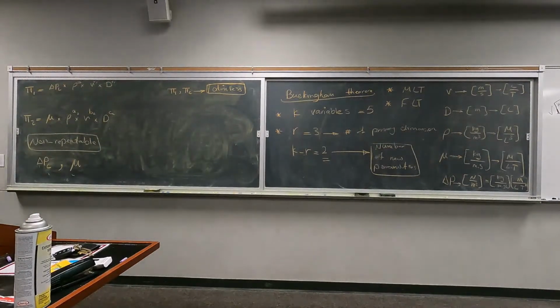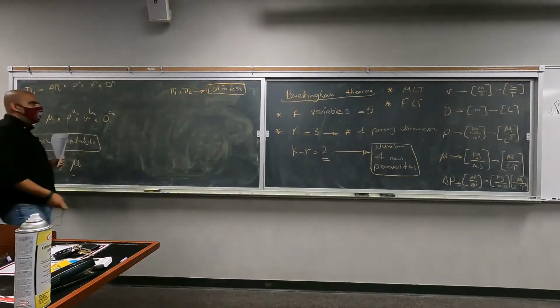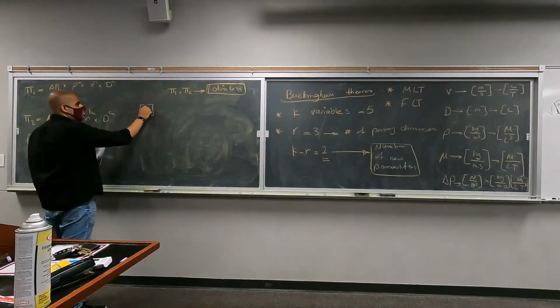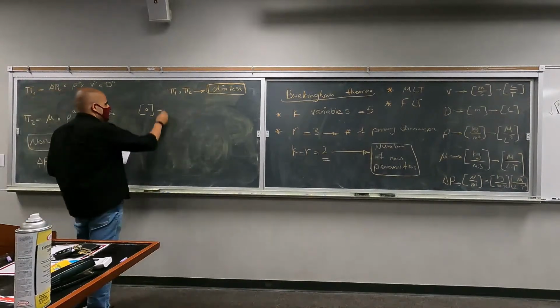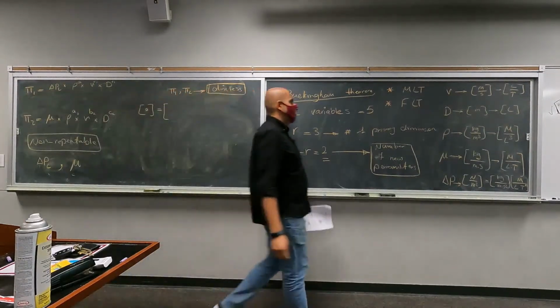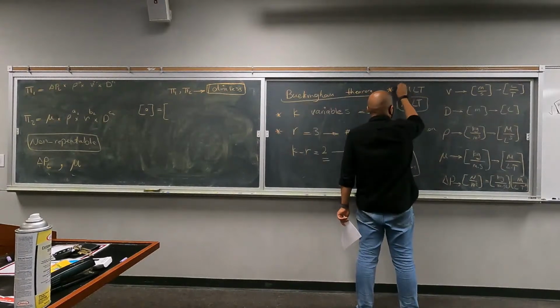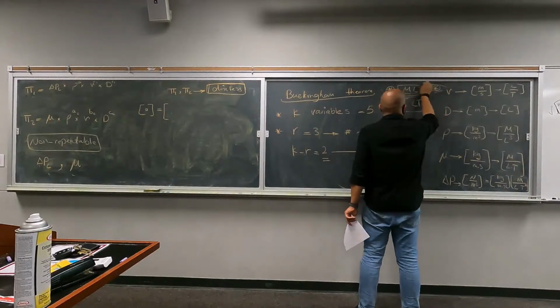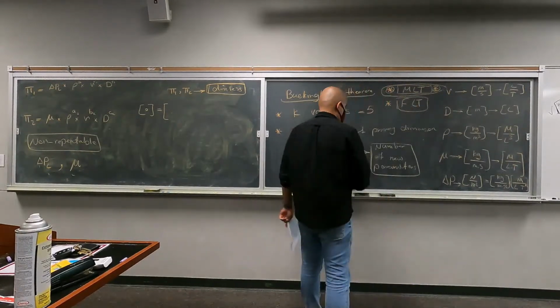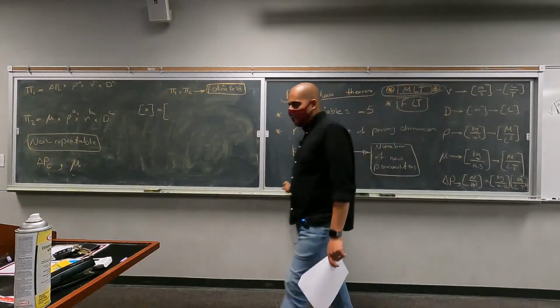And then your goal here is to choose these powers in a way that will ensure your pi1 is dimensionless. That's the next step. We already know that the dimension of this pi1 is 0. Okay, so let's do this for the first one. What was the dimensions of delta p? I want to use MLT method. You can use FLT method, doesn't really matter. But this is the method I usually use for myself. And it is a more common method, so I'm going to keep using that.